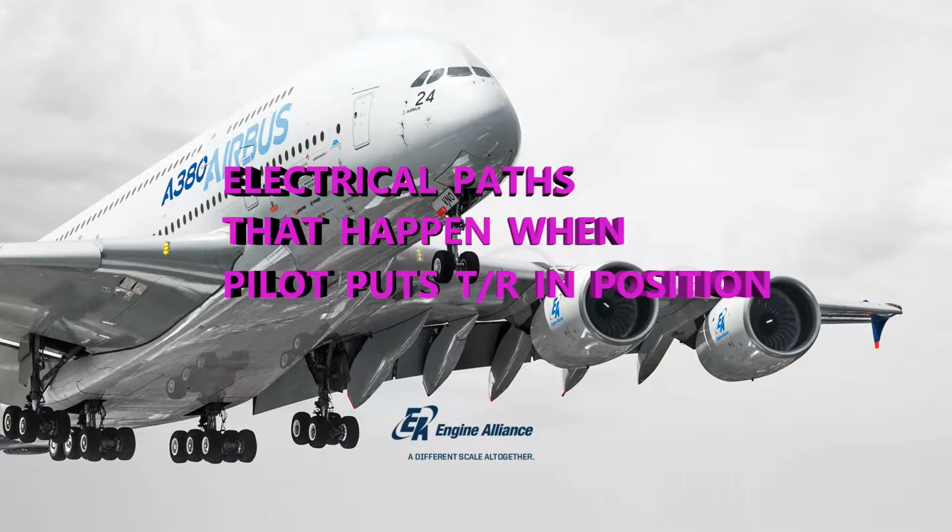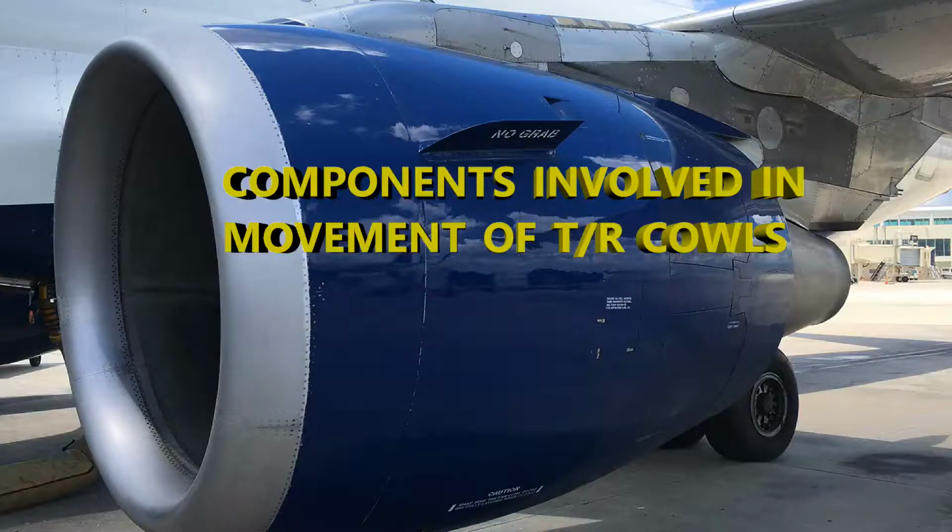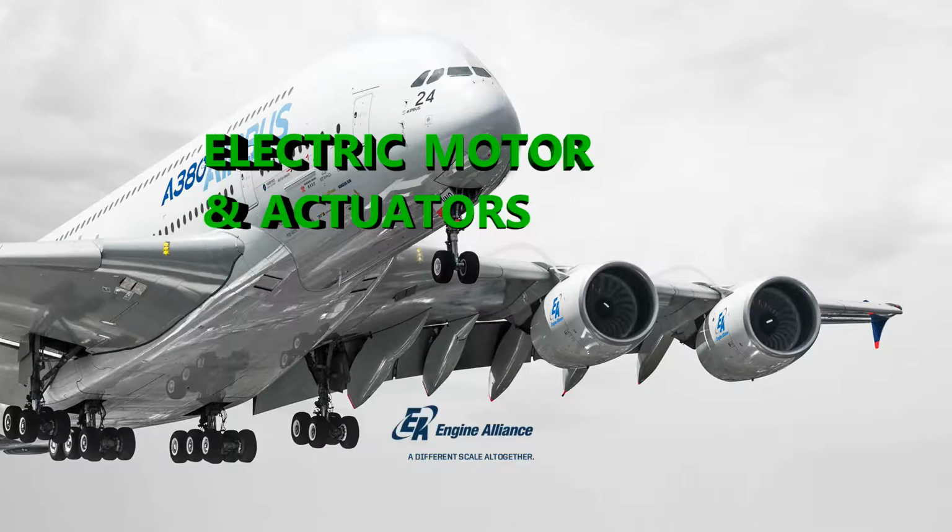All right, let's talk a little more about the components involved in the movement of the cowls. You have an electrical motor, like I mentioned before. You also have your actuators. There are 3 of them, and they're taking the rotational movement of the electrical motor and turning it into more of a linear movement.